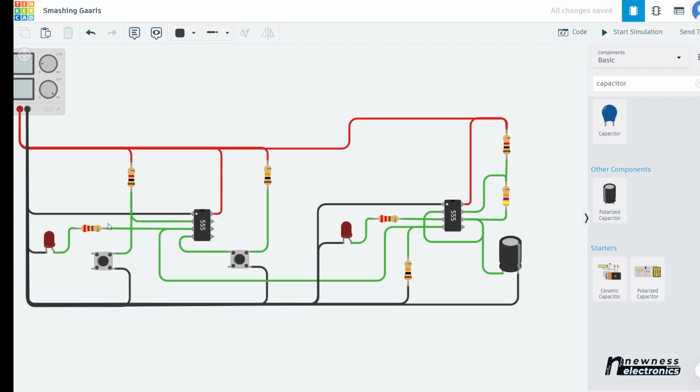So let's run this simulation. As long as this light is on, this also will be blinking. Let's see. You see now. Okay, the next thing now, what if we reset it? You see, this has stopped working. So we are using the output of this bistable to control this other astable. So let's start it again. You see that now. So this is a simple control circuit. So this is like an on button, and this is like an off button. All right, that's beautiful.